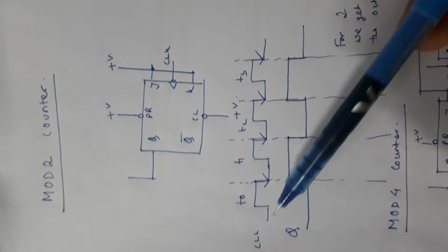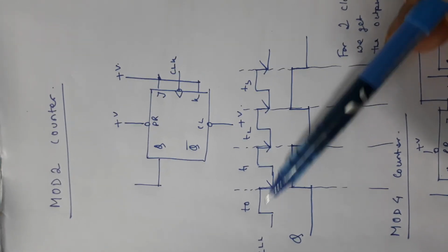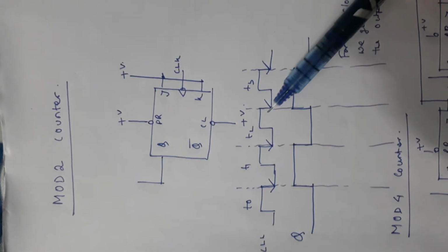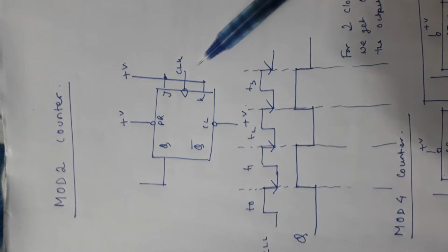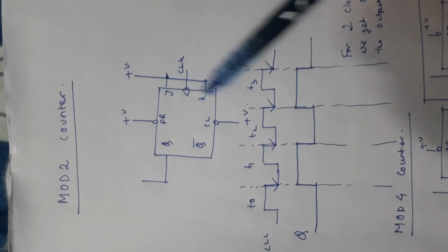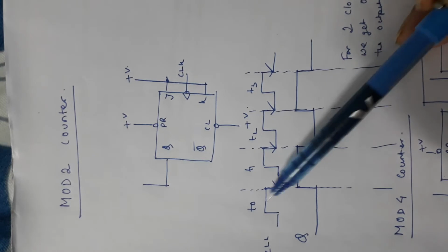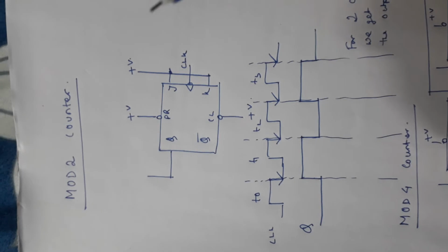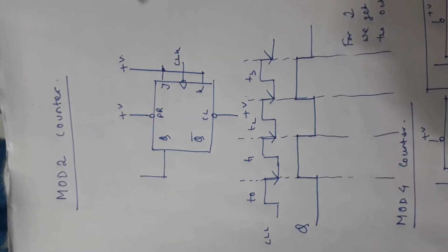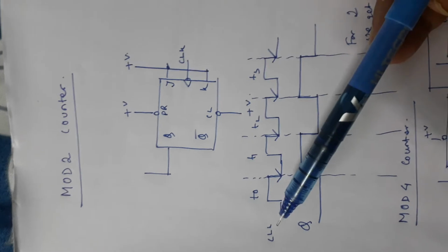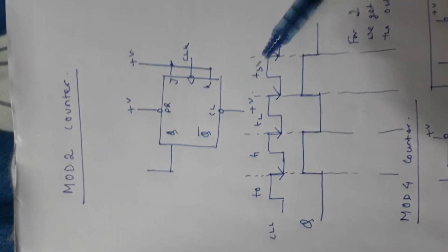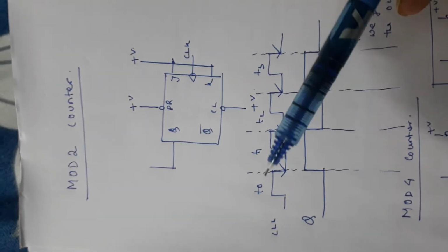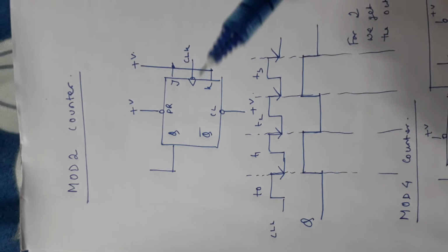See, this is the clock, right? We are having a train of high and low pulses, right? So this is the clock that is given as the input to this IC. And where from we are producing this clock? You can produce it from an IC 555 astable multivibrator that we have learned in your previous semester in analog electronics, right? So you can produce the clock of any period. Period, you can control it by the values of R and C in the IC 555 astable multivibrator.